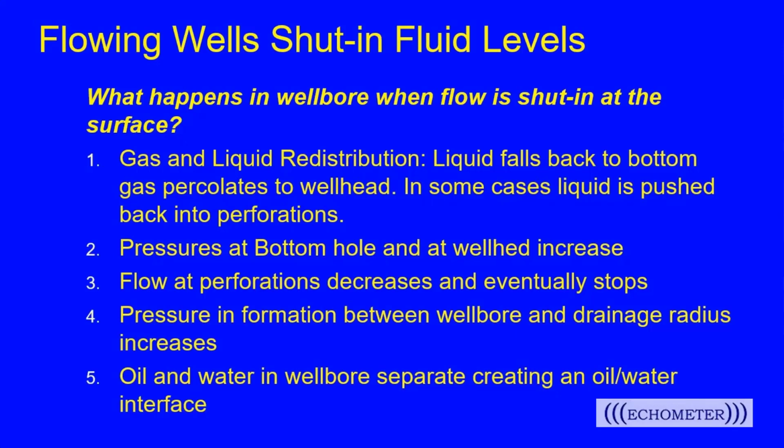So if they're separating like that, and our surface pressure is increasing and going to push fluid back into the formation, what's the first fluid that's going to be pushed in? Well, it's the water, right? Because the water is at the bottom of the column. So we'll have to monitor that liquid level and see what we have left, and use that to calculate how much oil and how much water we have in the well.